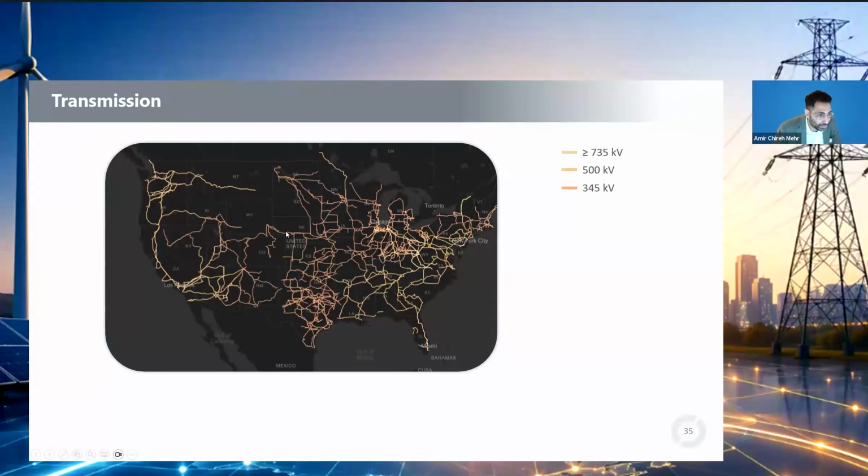If we go a layer deeper, we suddenly see much more connectivity. But still, keep your eye on the east to west connection: there's one power line here connecting the two, right? A way to envision that, electricity being less intuitive than water, as I alluded to earlier, is to imagine these are massive water pipelines or gas pipelines carrying physical stuff. There's one interconnection here. So if this is 100 gigawatts, 200 gigawatts worth of electric capacity, and the interconnection is 2 gigawatts, you can only import or export 2% of that capacity in either direction, right? So it's a giant constraint.